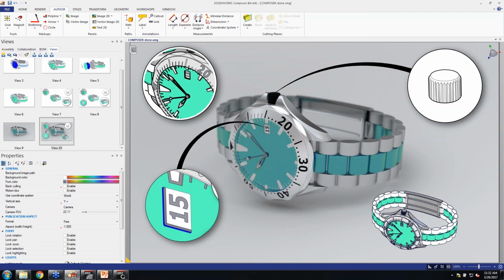And then once you're happy with it, we just go here and say we want to save it out. 1280, let's say 600 DPI, high quality. Make sure I have a single image. No alpha channel because I want the image in the background. I don't want a blank background. I like that image.